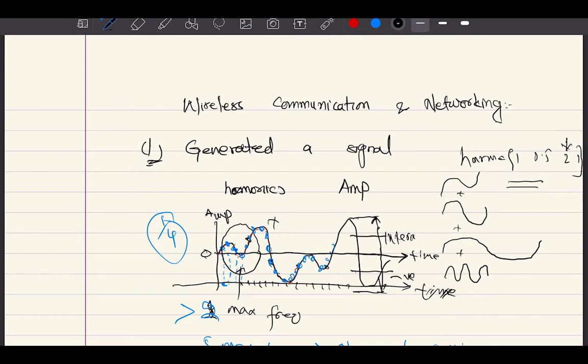I think we defined 4 levels for it. So 1, 2, 3, 4, we defined 4 levels. And then we started from this level and moved to the upper level, checking which signal points are contained in the first level, the second level, the third level, and the fourth level. So any signal points contained in this level will be located in this quantile interval. For example, this one and also this one. So all these points will be assigned to this quantile interval.